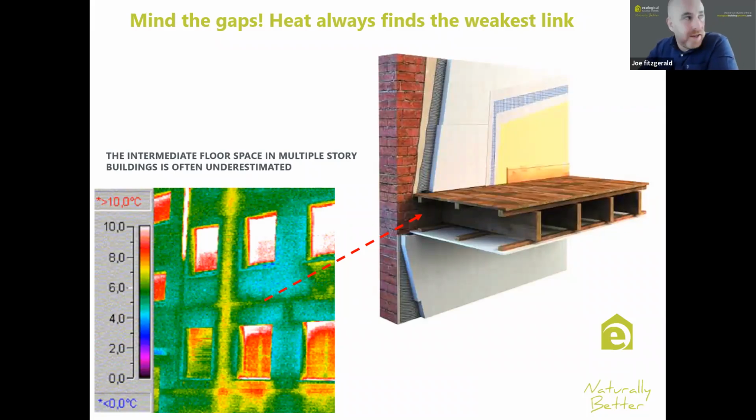It's not so much about heat loss, although it does have an influence. Typically the heat loss associated with thermal bridging, there might be some very experienced people in the audience in this respect, like myself, but typically you're probably talking somewhere between 10 and 30% heat loss, depending on the building. But this type of building, you'd be closer to the 10 mark. But it's not so much about that. It's more about the cold spots on ceilings, preventing mold growth, which in turn can have an impact on human health and indoor air quality.